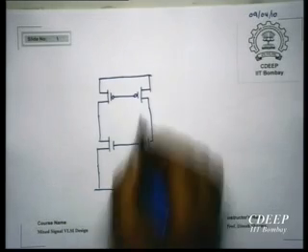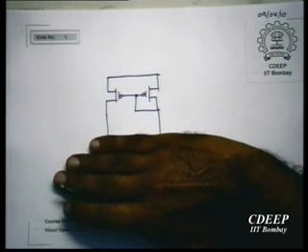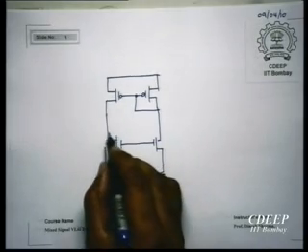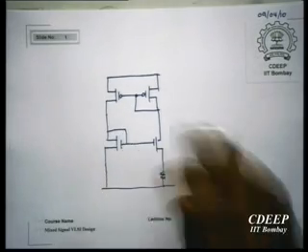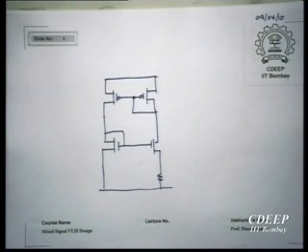The idea is that we have actually two current mirrors. If you just look at the top, this is a current mirror, and if you just look at the bottom, that's a current mirror too. Essentially, the beta multiplier is the result of somebody asking himself, what happens if I feed a current mirror by another current mirror? A current mirror requires a reference current: one reference current goes in, the other is the output current.